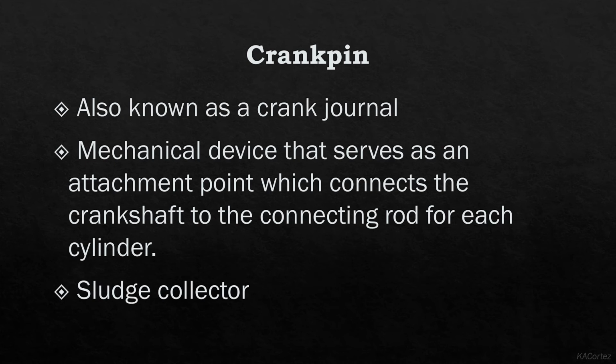To reduce total crankshaft weight, crank pins are usually hollow. This type of construction provides a passage for lubricating oil. In addition, a hollowed crank pin serves as a collection chamber for sludge, dirt, carbon deposits, and other foreign materials. Thus, it is also called the sludge collector.